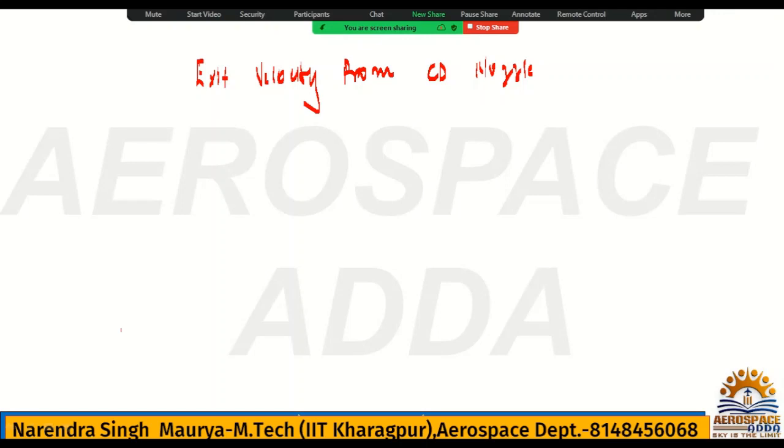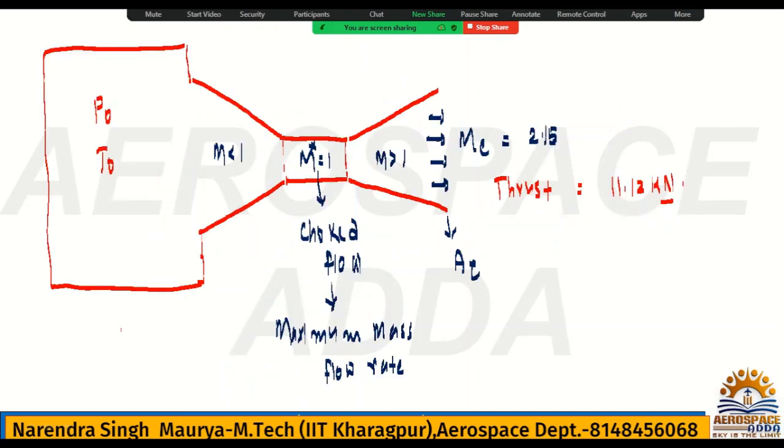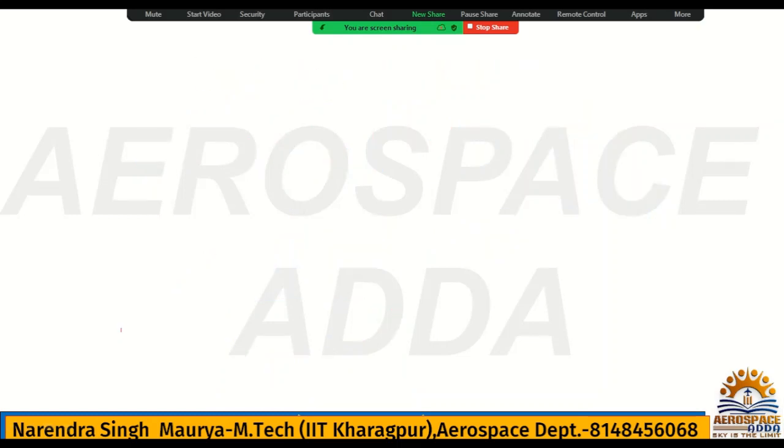Otherwise, one more thing you can do, if you think about it, then you will understand. I have given here that the throat is choked, and if the throat is choked, then mass flow rate will be maximum. That is also correct. So maximum mass flow rate from the CD nozzle or reservoir we had seen. If you use that formula, then also you can get the throat area. Once you get throat area, you can get exit area. Otherwise, you calculate exit area, then you calculate throat area, because you have the ratio. So both ways we can go.